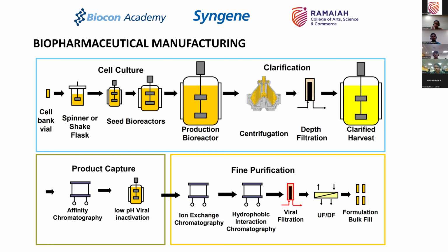Sometimes the product in the liquid is of interest, sometimes it is the solid which is of interest, depending on whether the product is intracellular or extracellular, because your product can remain within a cell or can be growing extracellularly. So if it's extracellular, then generally it is present in the clarified liquid, and you need a clearer liquid. Or if it was intracellular, then you will probably end up having the solid, which is of importance. Both of the processes are possible. Here we are talking about the liquid being of importance, so the product was coming out in the liquid.